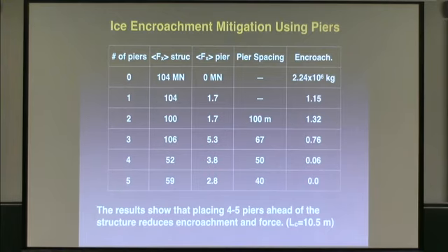The other question is a physical one. When you compare the 2D simulations with the HSVA lab experiments, you saw the spiking in the forces, and you associated that with individual buckling events, and no doubt you're right. But what about the incorporation of stick-slip friction? You're probably using a constant coefficient of friction. If you use a rate-and-state law, you could get some peaks in forces. We have found that when we've done experiments.